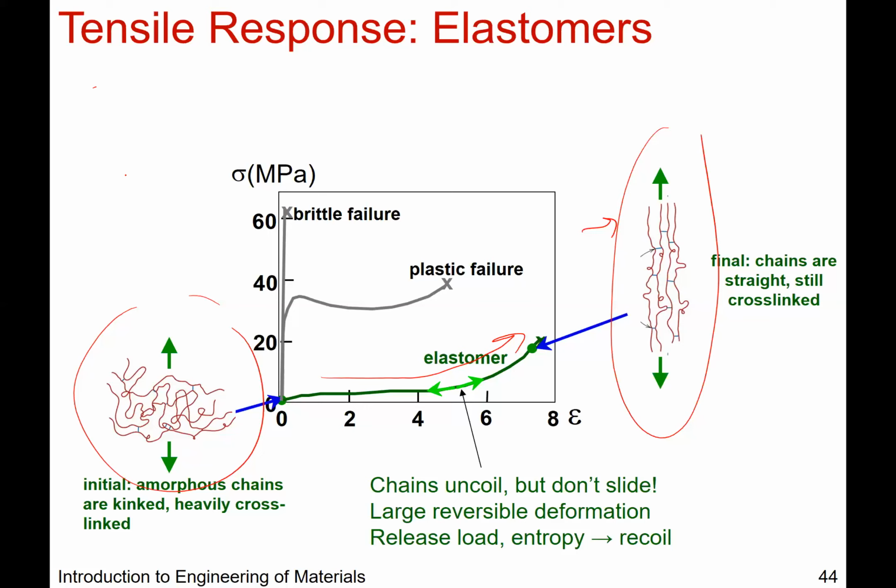So to jog your memory, for a metal, if you apply stress to deformation, release the load, it will recover some elastic strain. But then let's say you apply the load again, it will continue, but its initial strain, excuse me, is not going to be the same. Okay, so two different cases is all I'm saying.